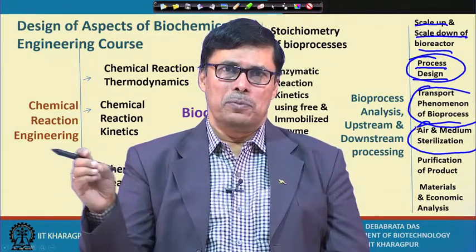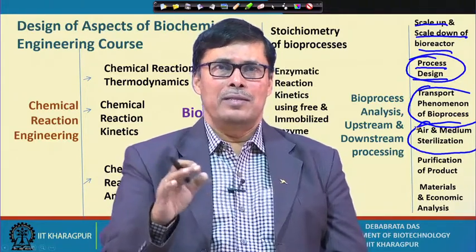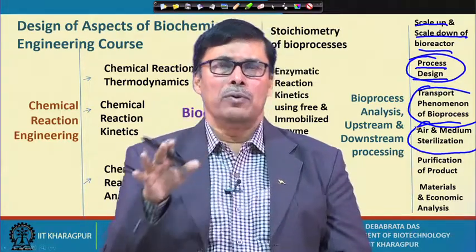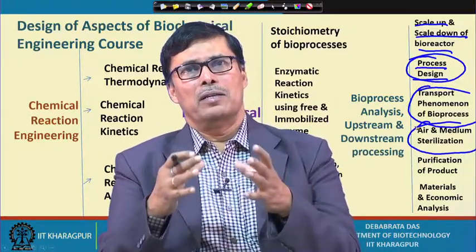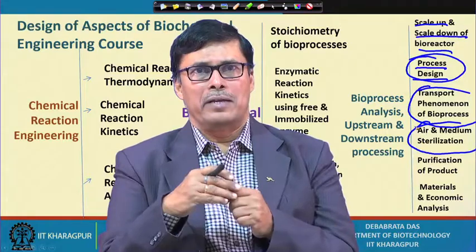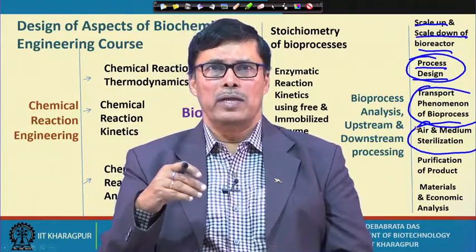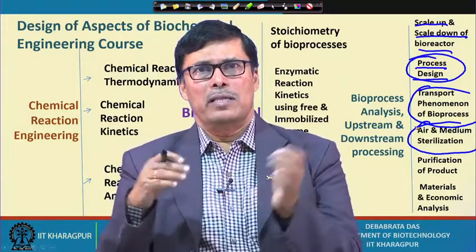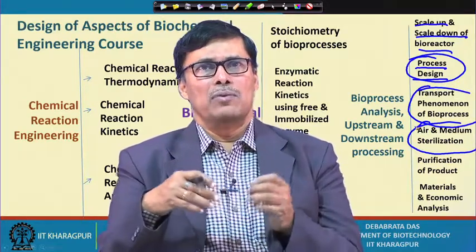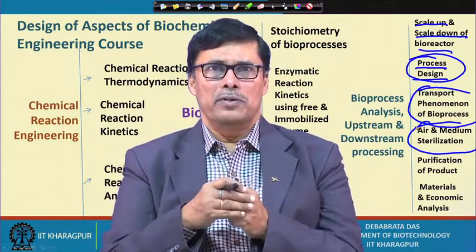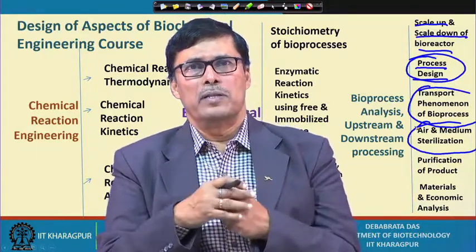Suppose we sparge the air through the bioreactor, that is the moving air, and stagnant air means suppose we want to do some kind of operation in this particular room, then the room is to be sterilized, that is the stagnant air. For stagnant air sterilization, usually we use UV rays or germicidal spray that sterilize this environment. But for the moving air, usually we use a physical separation technique. We use some kind of filtration technique just to remove the contaminants present in the air.